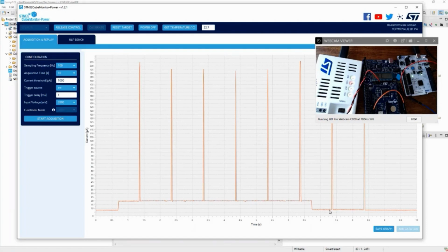You still have the RTC interrupt. And the RTC interrupt will detect that there is no activity at the second one, and it will display idle and stop the RTC interrupt. So this is what you see here, and this is what we have done. And you see the nice consumption, which is approximately 7 microamp.